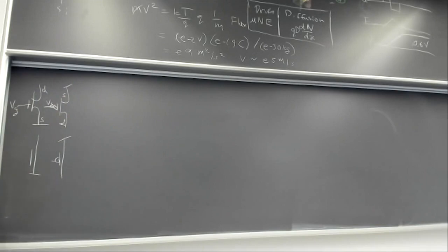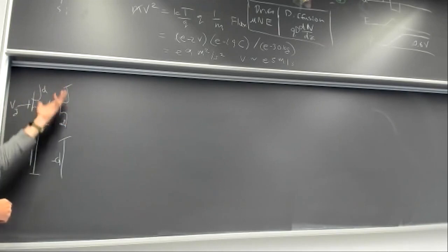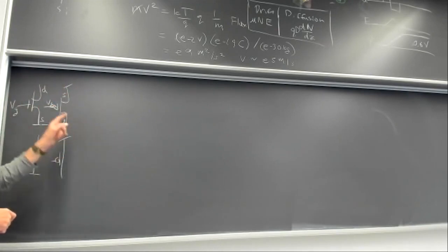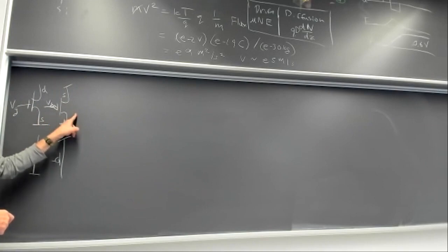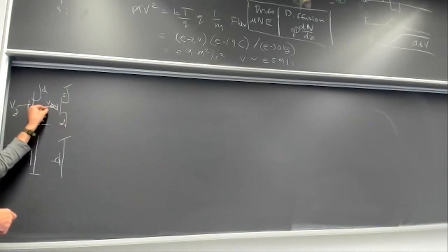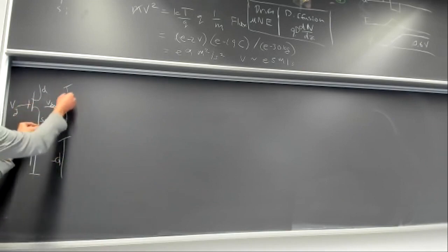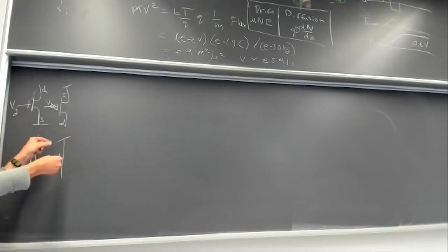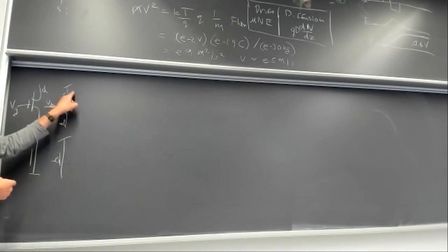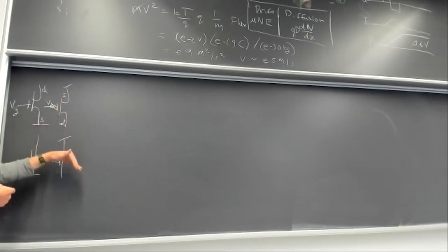Okay. But everything I tell you about NFETs applies for PFETs, except that the voltages are flipped, right? To turn on this PFET, you have to attract holes into the channel. How do you do that? By putting negative charge on the gate, making the gate more negative. That makes it easier for positive holes to get into the channel. Is it clear? And then the voltage that matters is this side, right? This is just where they fall out. It's like the bottom of the waterfall.